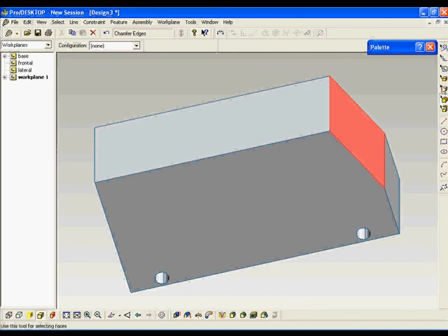The next step is to go in and select several different of the edges, the vertical edges, and we're going to round the vertical edges of the van body. So as I go around, I'm going to hold the shift key down while I select the different vertical edges, vertical meaning the ones in the Y direction.